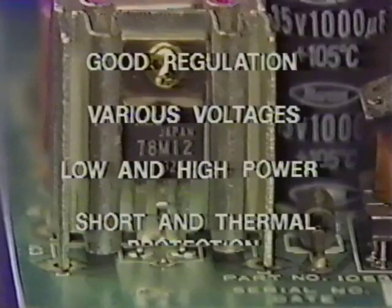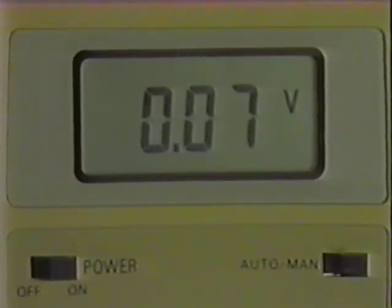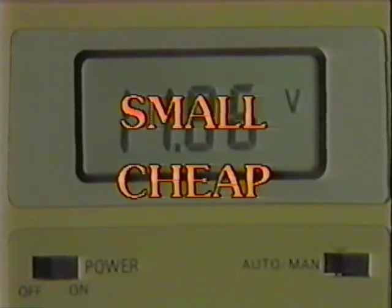They are protected against thermal and direct short overloads. If an excessive amount of current is demanded by the load, the regulator automatically shuts down by reducing its output voltage. When the load current is reduced, the regulator automatically restores its output to its rated voltage. Finally, the 3-terminal regulator provides the advantages of all ICs: less board space and lower cost.